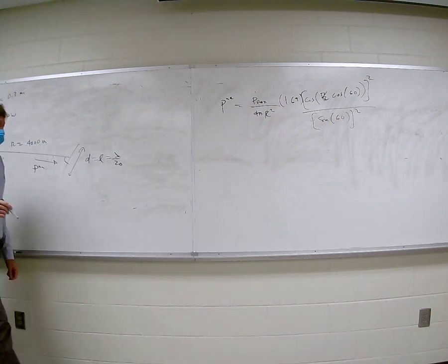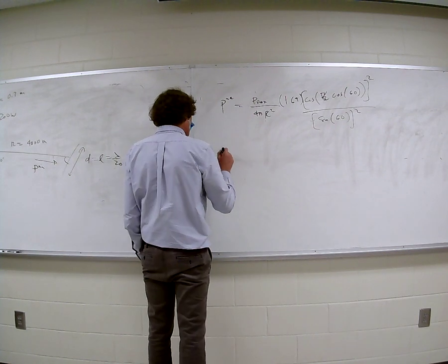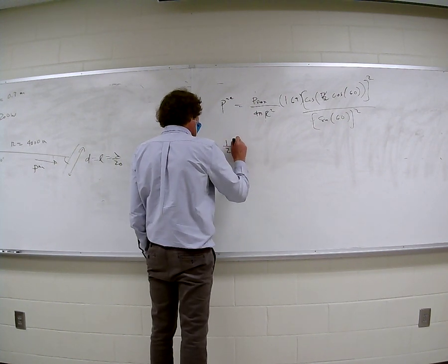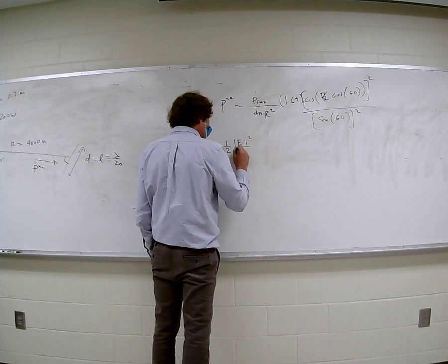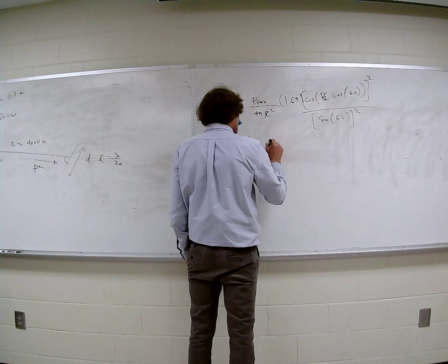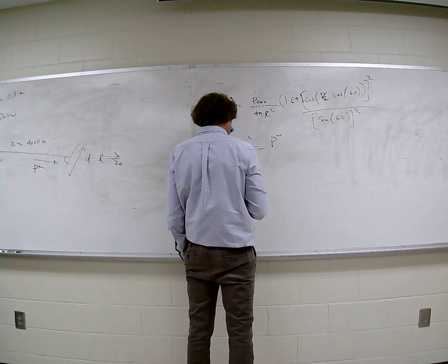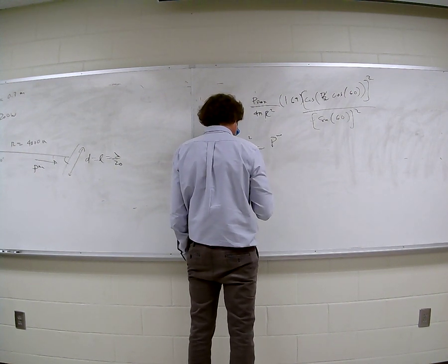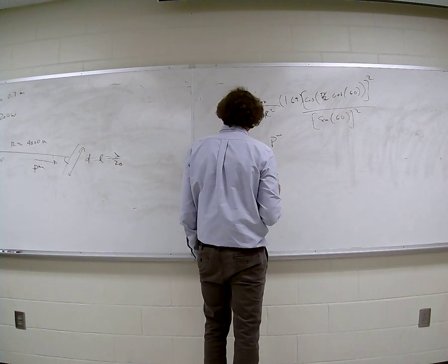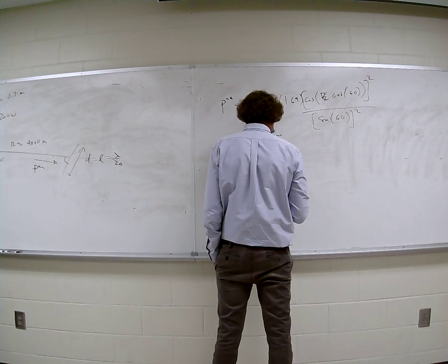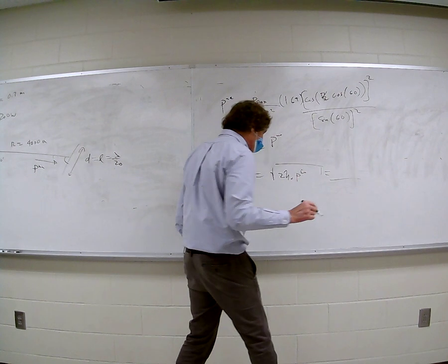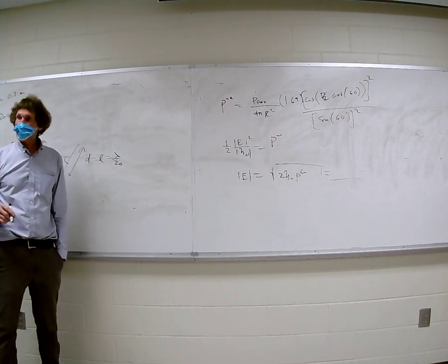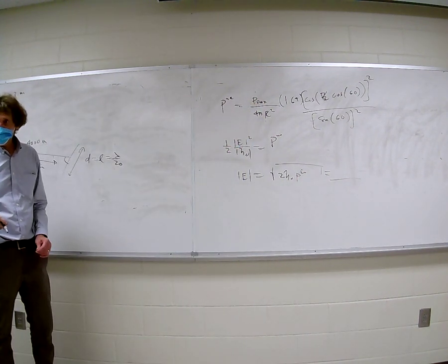All right, well, the electric field, this is free space, so you know that one half magnitude of E squared over eta is equal to P incident, and therefore the magnitude of E on that second antenna would be equal to the square root of 2 eta times the incident power density. That would be in volts per meter. I didn't care about any kind of vector notation here, just wanted to see what the values were, right?